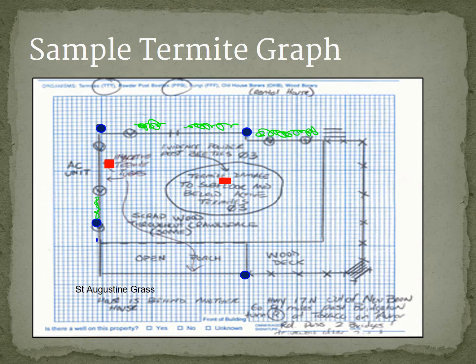So obviously you'd have a couple different options, but I think a lot of times we probably pull up the two boards closest to the house, kind of pull them up easily with a little crowbar. We may tell the customer if the wood's really old, it may have to be replaced, but we've definitely got to at least pull it up, treat that area, and either put it back or replace it with new wood, because we have to wrap this whole entire structure to really be effective in termite control.